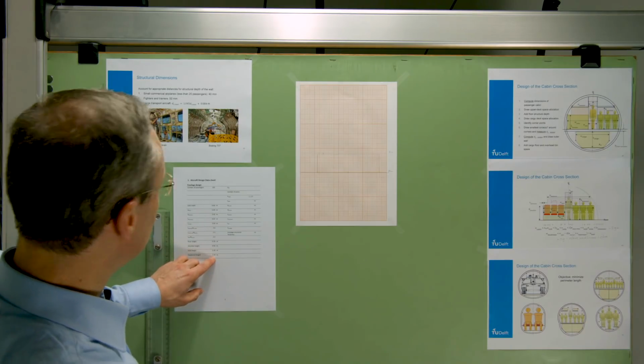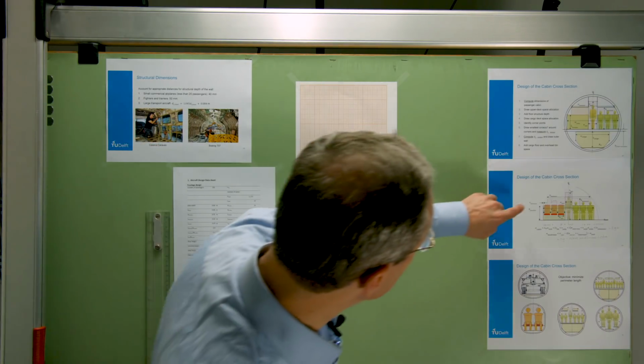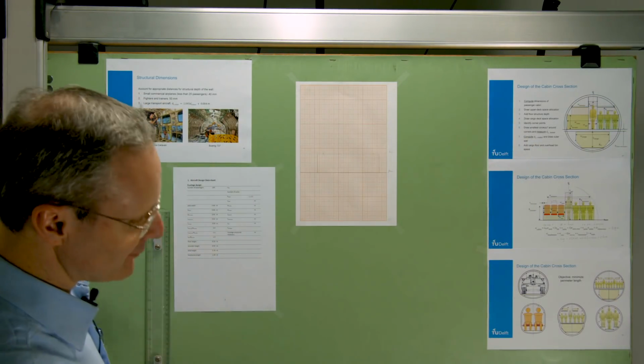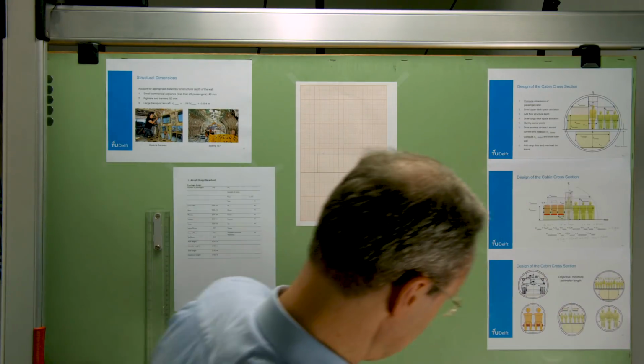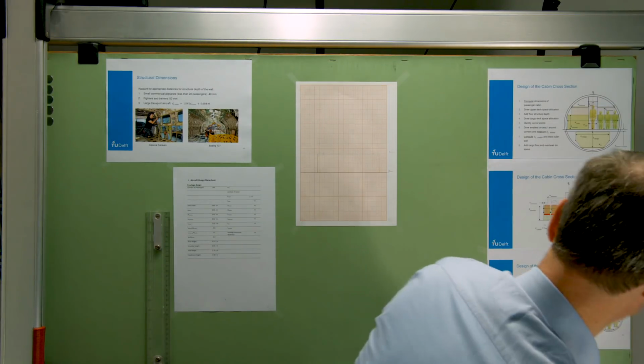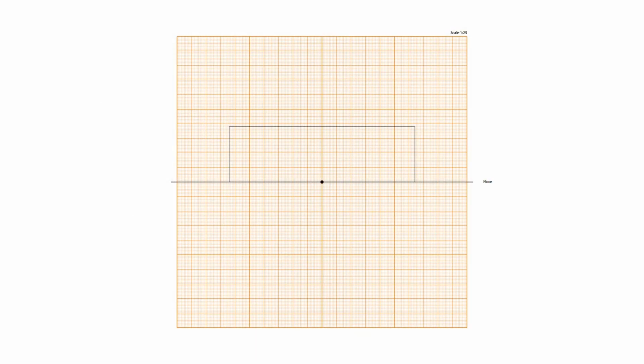And then we need to also draw in the headroom height. So this height we have over here has been given as 1.5 meters. 1.5 meters, 150 centimeters divided by 25 gives me 6 centimeters, 60 millimeters. So we need to go up from the floor at this point to a height of 6 centimeters. We'll do the same at the other side. From the floor, nicely perpendicular, we go up to 6 centimeters.